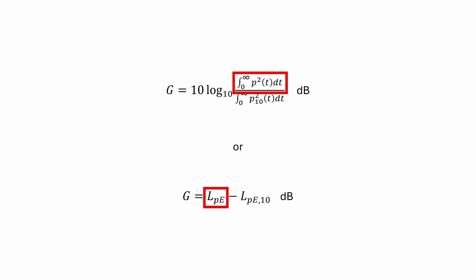It is the ratio between the sound pressure level produced at a receiver point in the room and the sound pressure level at 10 meters in a free field while using the same source. The problems with deriving G lie in practicalities. First, even though G is a relative parameter, it still requires measurements of SPL, which cannot be performed on a PC unless the signal chain was somehow calibrated with a reference SPL. The second is the impracticality of finding a free field where we can set the source and receiver 10 meters apart. However, it is possible to indirectly derive G using only relative differences of SPL.